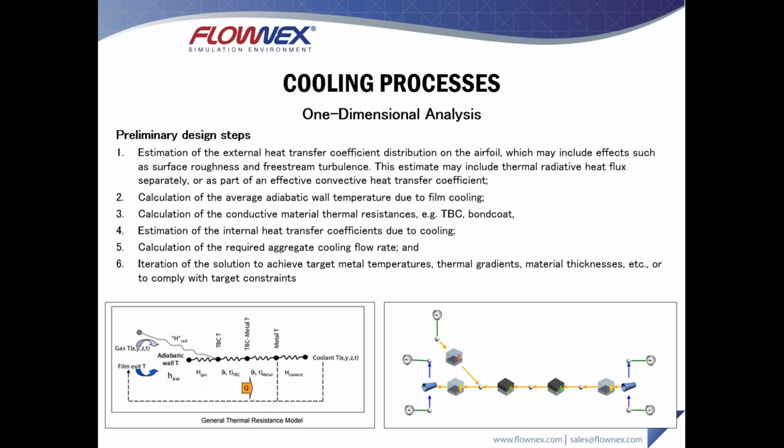We have heat transfer components for modeling film cooling, and it allows you to calculate an average adiabatic wall temperature. We can represent conduction through multiple solid materials with multiple layers, so you can have your airfoil metal material covered in a thermal barrier coating or whatever it may be.